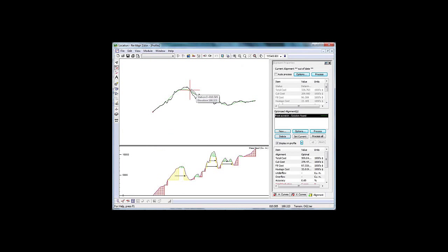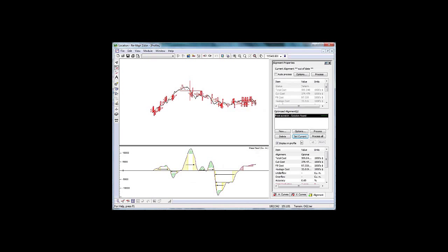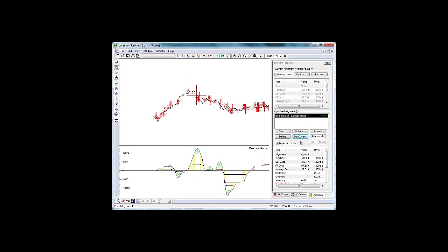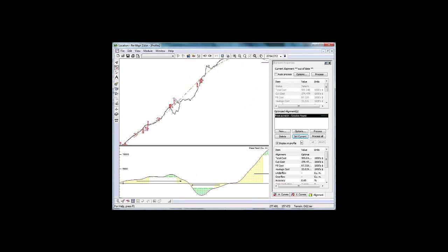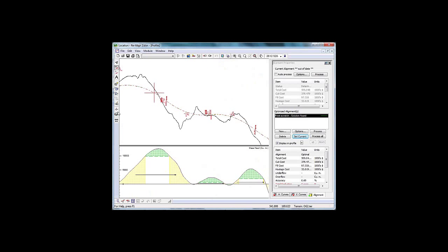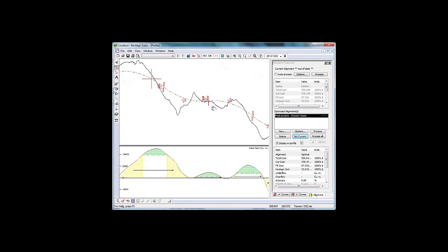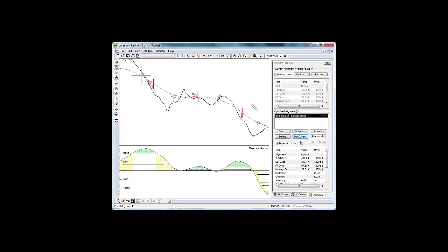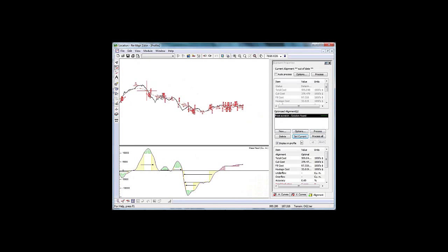There it is. So that green line was my vertical alignment. Then I can set that as being a road edge alignment, recalculate, and I can see all the curves and intersection points and so on that were created by the optimizer. Whoops, this one was created with some different parameters, so I got curves bumping right into each other. That's my mistake. Normally you would, well, not normally, but there are situations where this might make sense. It's just an option I had set wrong when I calculated that alignment.